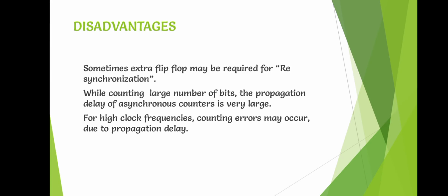Disadvantages. Sometimes an extra flip-flop may be required for resynchronization. While counting a large number of bits, the propagation delay of asynchronous counters is very large. For high clock frequencies, counting errors may occur due to propagation delay.